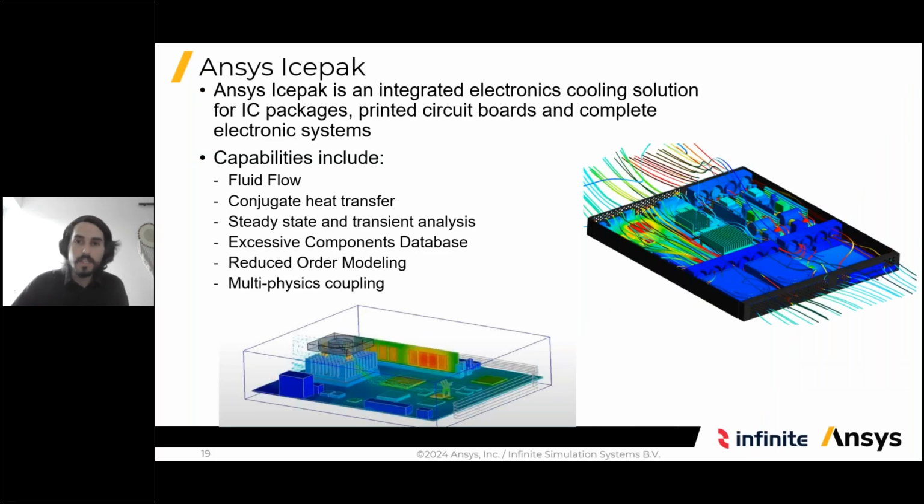The tool is called IcePack. IcePack is a solver for thermal management. It does a finite element analysis of the airflow or the heat transfer of the convection. So there is a flow field, and we are then solving the Navier-Stokes equations within this field. It can simulate both steady state and transient analysis as well. There is also a very big database with components coming from manufacturers themselves, such as heat sinks, fans, etc. This is, of course, to make our life easier. Lastly, it has capabilities of reduced order modeling, as well as coupling with other physics solvers, which I will touch upon a bit later.